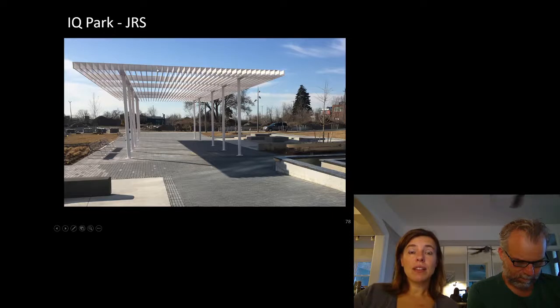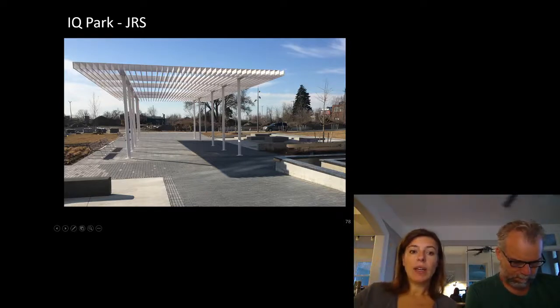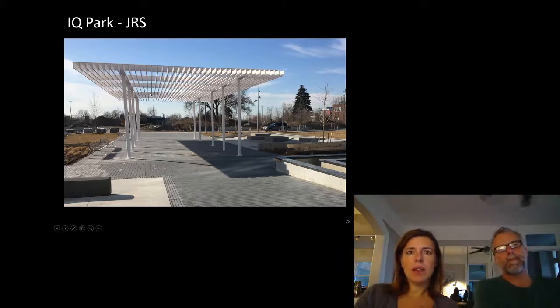So these are a series of custom aluminum mullions connected to steel HSSs, and the columns are cantilevered up for wind load.